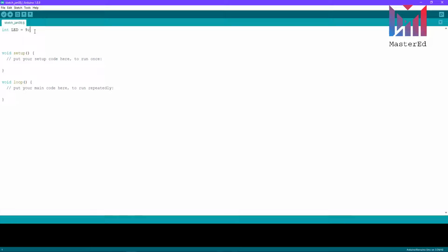The reason why we use PWM pins is that these pins are specifically connected to use built-in timer to generate the square wave. And we need that option to regulate the brightness of the LED in the fade project. Okay, so the next variable is brightness, which must equal 0 in order to give our LED 0 brightness from the beginning. We need the third variable as well.